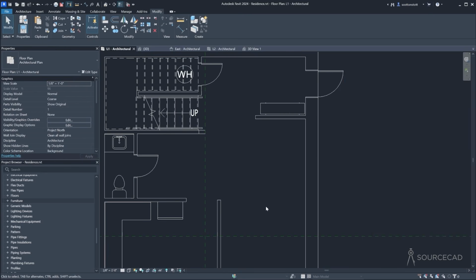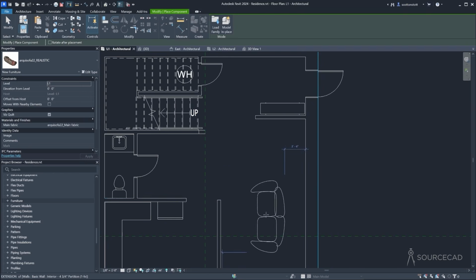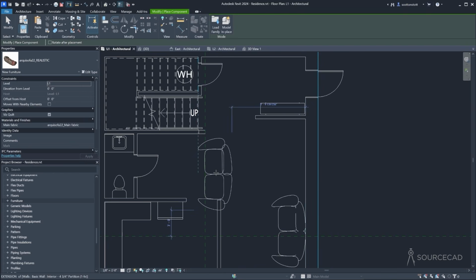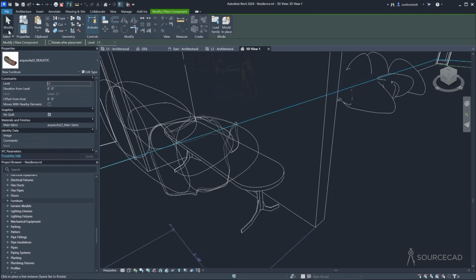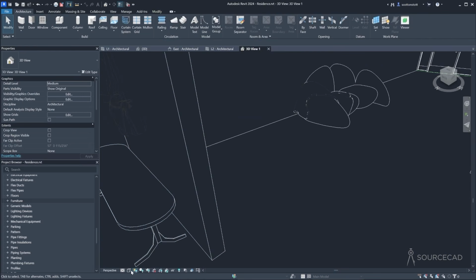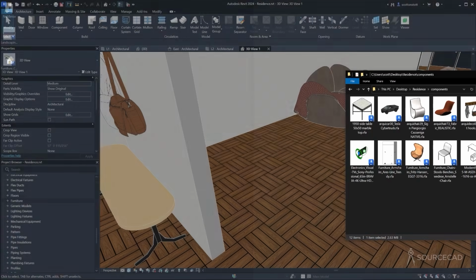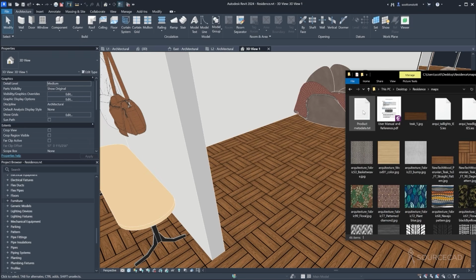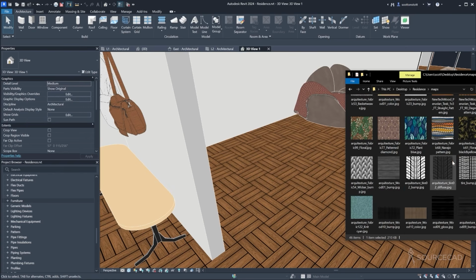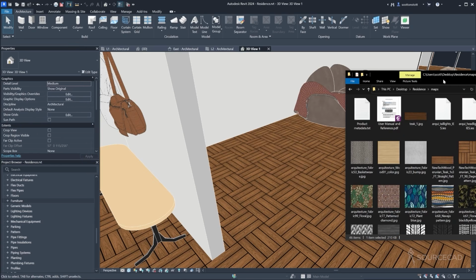So if I pull that in now, maybe it'll find the textures. Let's see. Now, I won't know if it has the right textures on it until I look at it. And I need to look at it in a mode that shows textures. Yeah. So this piece of furniture has texture maps on the furniture itself and on this blanket. And those are in my maps folder here. So these textures came with the download, and I put them in this folder already so that they can be referenced. Without that, your models will not be very realistic.